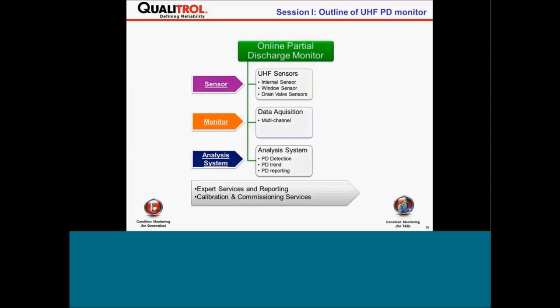The monitor itself is really just a data acquisition system, which samples the data coming from the sensors, formats it by phase resolving it to the power cycle, and then analyzing it, plotting it, trending it, reporting on it is the final analysis section. And eventually we will have expert services or an expert system to automatically analyze, or at the moment we're doing very much expert services reporting on what we see.